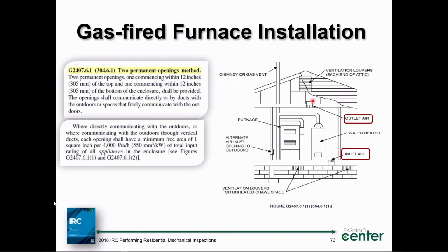You check it as building plans examiners. I hope you do. Maybe you have soffit vents over here. Maybe you got a ridge vent or gable vents, right? Certain area based upon the square footage of the attic space, whether or not you have a vapor barrier, right? It's either divided by 150 or 300 or something like that. But it's got to be properly ventilated. We're not going to go into that part, but if it is, I'm going to take it from the attic space.